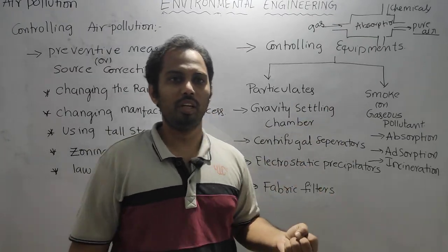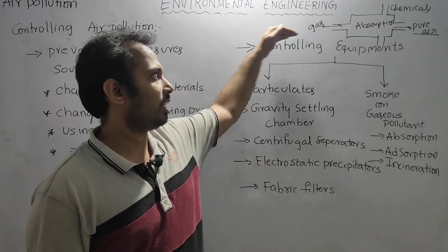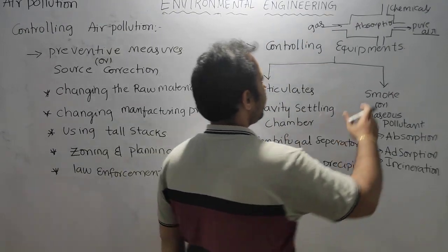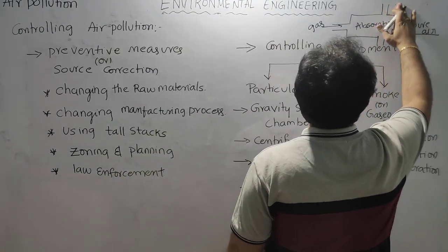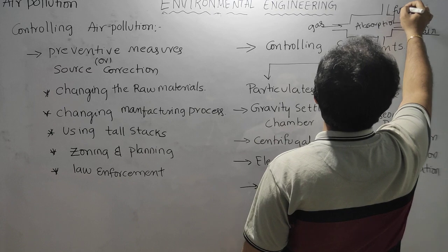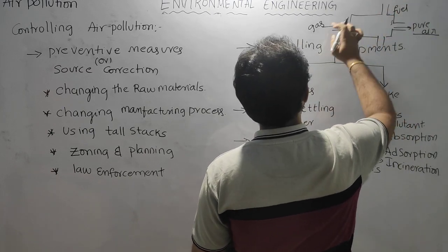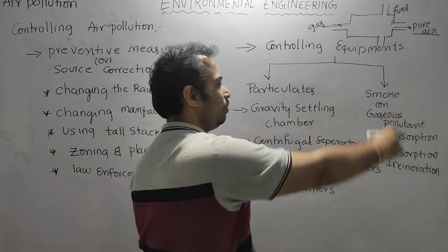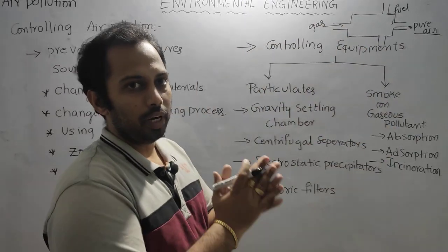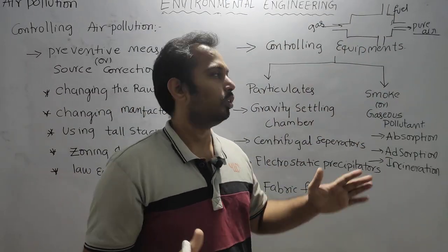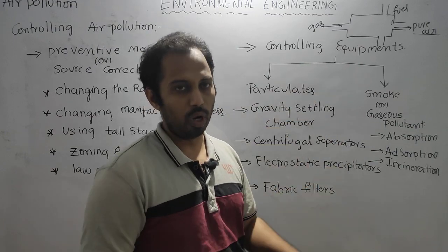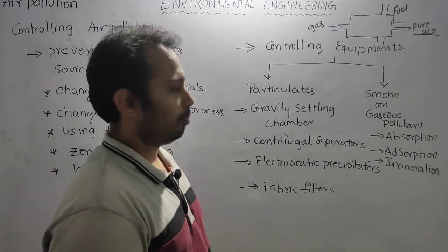Incineration means we send the gaseous pollutant into the chamber, and along with that we give some fuel. The fuel and the gas containing pollutants undergo complete combustion, so the pollutant is removed due to the combustion.